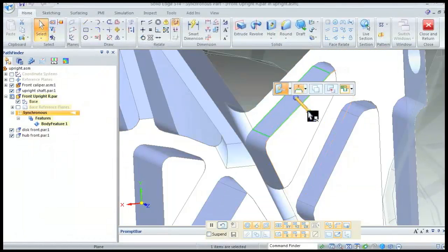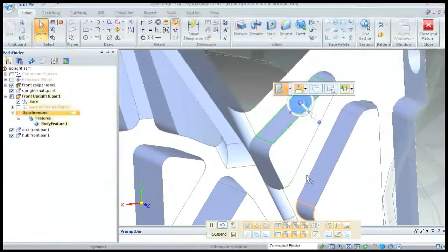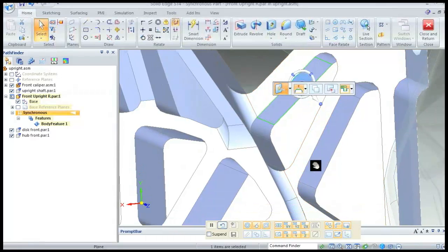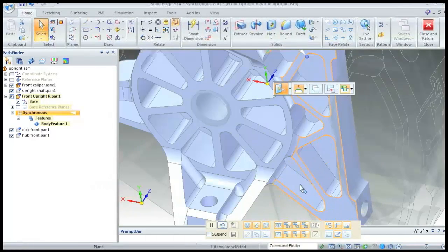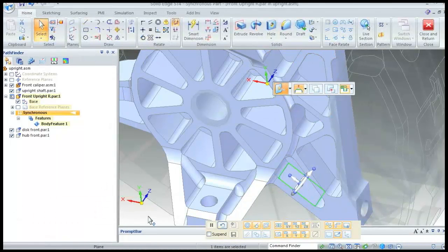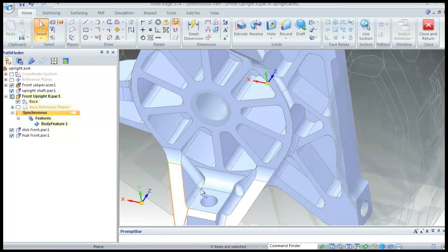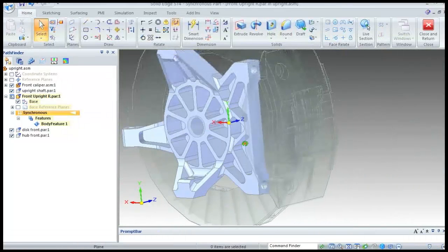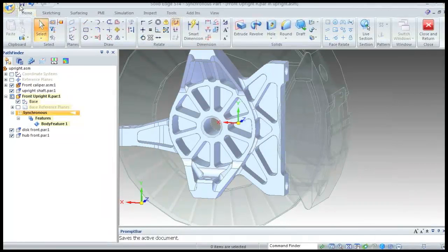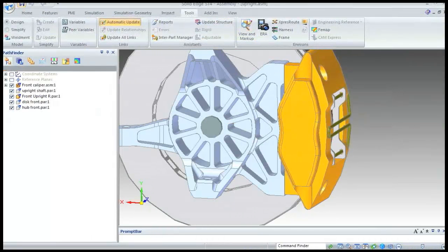Just drag spaces. We've seen some high stress there, so let's just add a mirror to that location. It's just space as well, and let's use the radius in here as well to probably put a bigger radius. Okay, so back to our model there. Save the model.